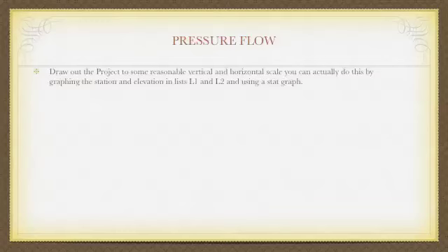All right, so this has to do with pressure flow when you're looking at Moody diagrams. Realize that everything is going to be Bernoulli's equation, but when we get to open channel flow, Manning's equation and the like, the hydraulic grade line and the energy grade line will be exactly the same because there's no pressure on the surface.